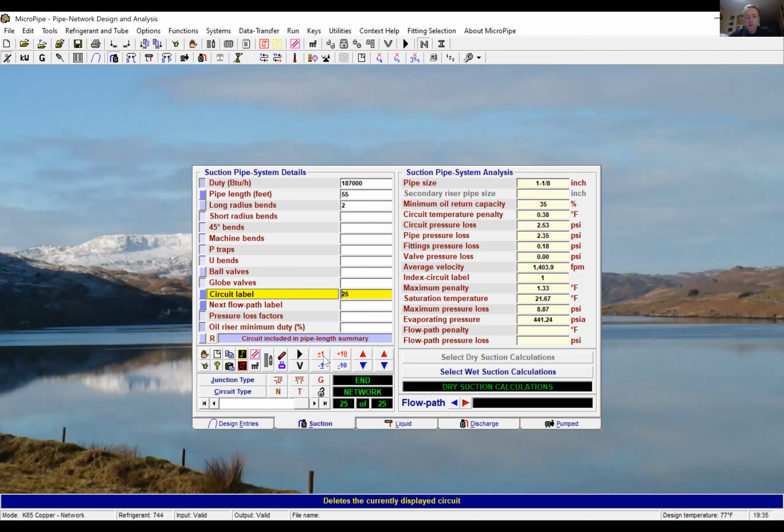I don't know if you can see the cursor of my mouse. Here, obviously I built it up by hitting +10 twice and then the individual circuits 5 times to get a 25 circuit network. Effectively, if you've got a customer and you've done a design and they've decided to add some more cabinets or take them away, you'd need to go back to your sketch for sure and do a little bit of renumbering, but you can add circuits into a circuit.